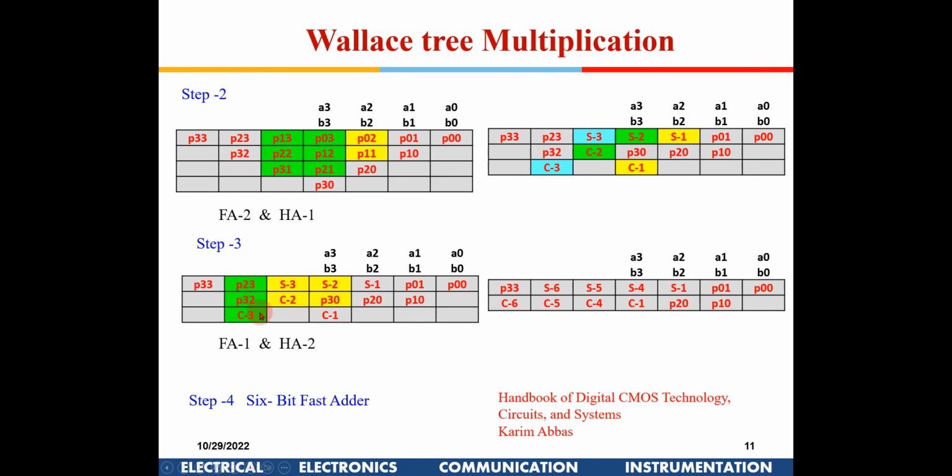Okay, because if you see here, there is a carry which is going to come here. So it will be 3 actually. Because I am going to put a half adder, there is going to be a carry which is going to come here. So that is the reason I have put a full adder out here. Is it okay? Because I have just split this into 2, but you have to see whether there is a carry going to come here. There is going to be a carry from here. So that is the reason I have considered this as 3 and put a full adder here.